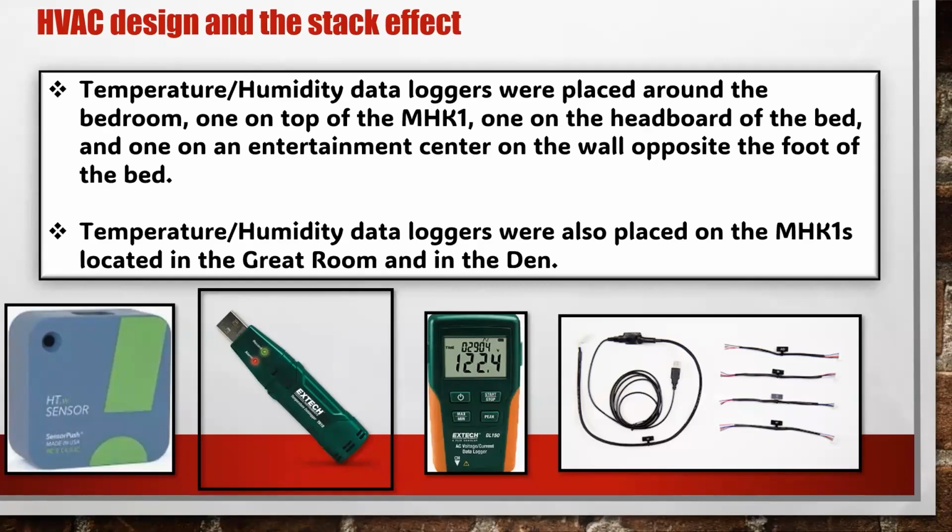Do those perform as well as a 36 air handler, as far as airflow and performance? Obviously the ductwork being sized properly. Sure, that's the key. If the ductwork is sized properly, yes, it works fine. Okay, cool, then it's interchangeable. I just wanted to check because the biggest one I've ever put in is like an 18, so I never went any bigger than that.